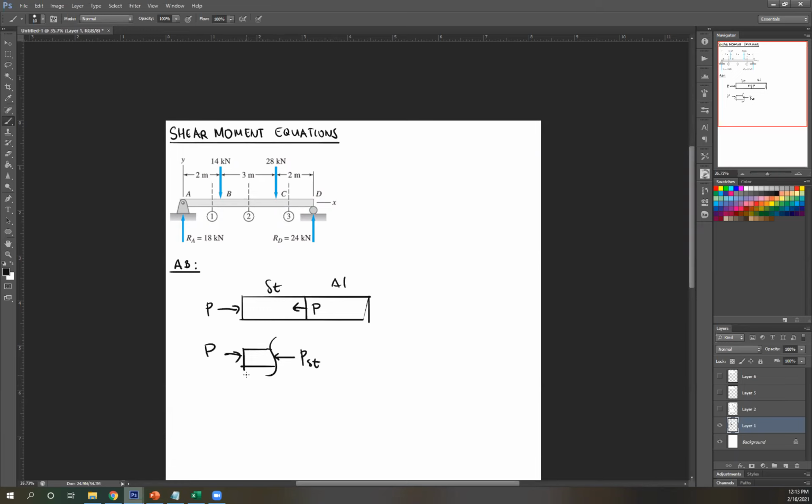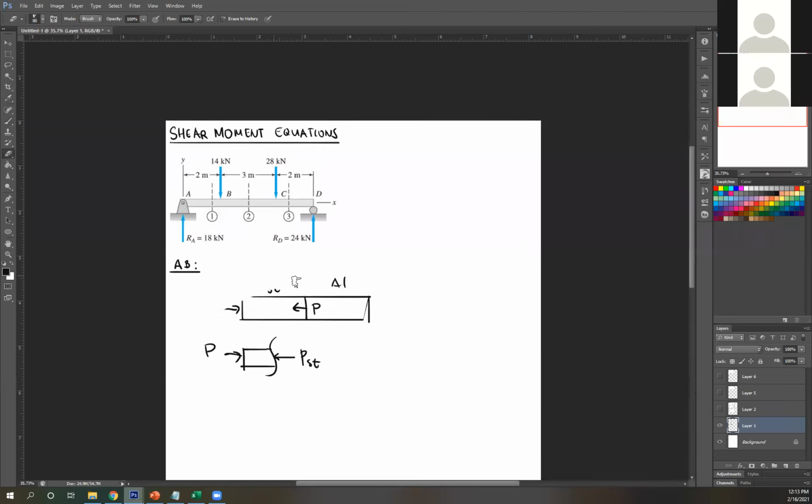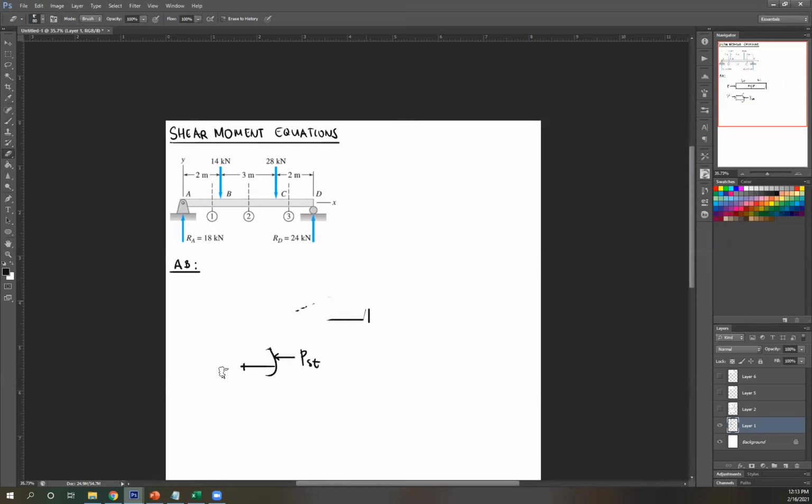All right. So this is the same thing for beams. Everything you've learned from the past topic, just apply it to your beams. The same thing, right? So let's do that. Again, we're at section AB. I'm gonna cut it, already denoted here. You're gonna cut at those sections. Then you're gonna isolate either the left or the right side, whichever is easier. Now for here, it's gonna matter what side you're gonna take. For section AB, obviously the left side is easier to isolate, right? So let's isolate the left side.